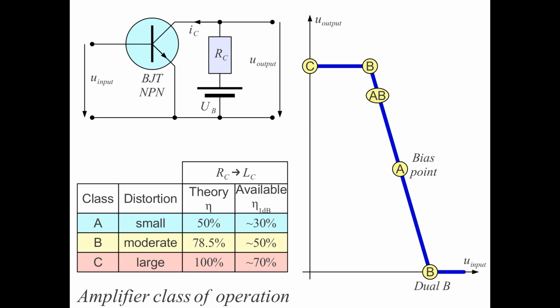There is no bias point with these devices. But with simple devices used in electronics, like vacuum tubes or transistors, we can adjust the bias point, and we can influence the efficiency of the output stage, though probably at the cost of a higher distortion.